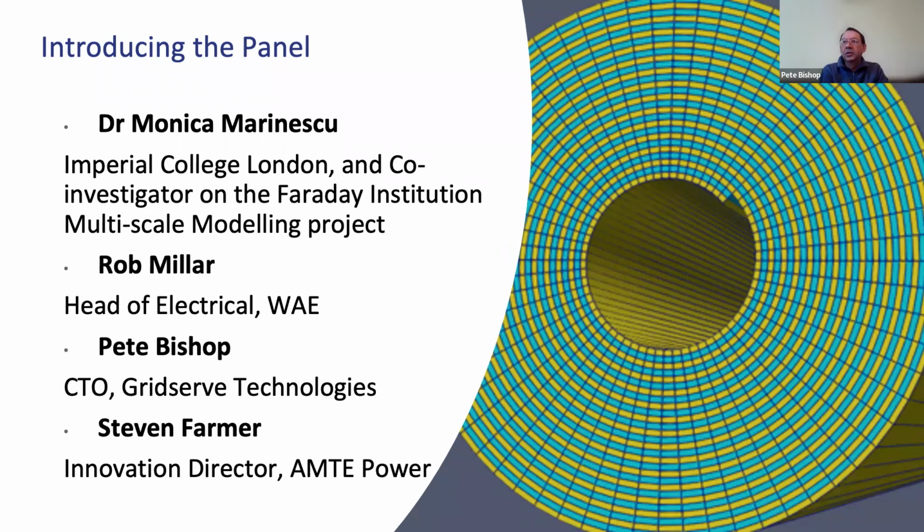Well, as you say, Peter, we work with a number of smaller niche vehicle manufacturers who typically don't have battery expertise extensively in-house. And we've been supporting them with modelling batteries for powertrain design, developing digital twins, etc. Really to determine things like BMS calibrations, but also with the power of modelling, we can look at what's happening internally within the cells, particularly looking at fast charge limitations.